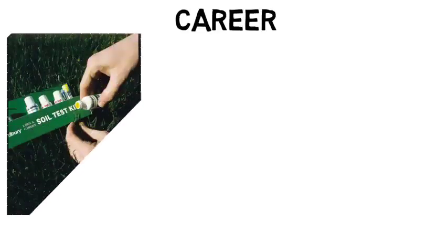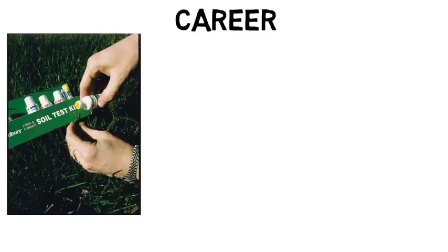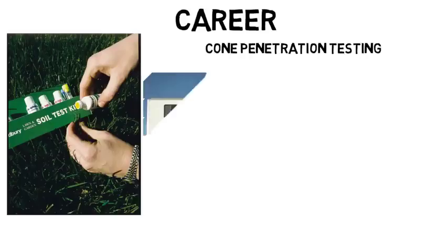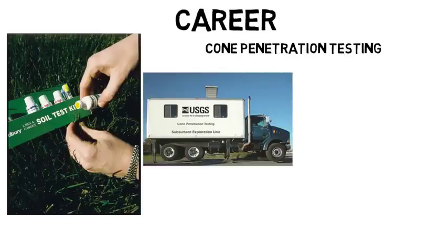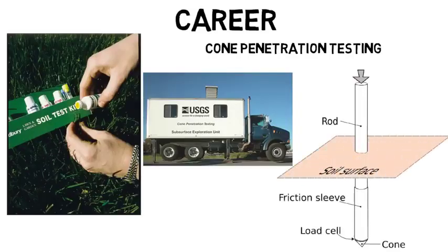You might be the person who goes out to the field where a structure is going to be built and collects soil samples all around the area for testing. Or you could do testing at the field. One of the most used tests right now in this field is cone penetration testing, where a large truck goes out to the field which has all this equipment on it, and a cone is pushed into the soil, and the pressure will be monitored by a computer on the truck as it moves through the soil into the earth. Based on the pressure, you can analyze the soil mechanical properties.